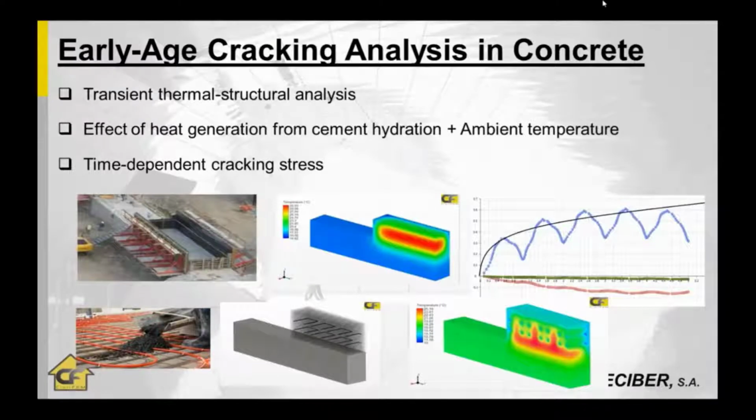So seeing in detail this model, the early age cracking analysis in this concrete. This is based on an old example we also saw in a webinar. What we did is just activating a new layer of concrete. We have on top of this added the ambient temperature with the variation day and night, and also the effect of the heat generation from the cement hydration.